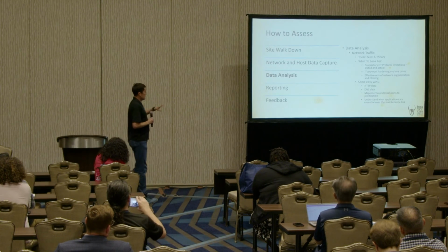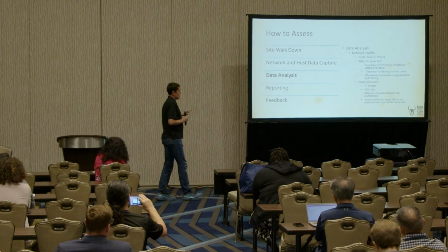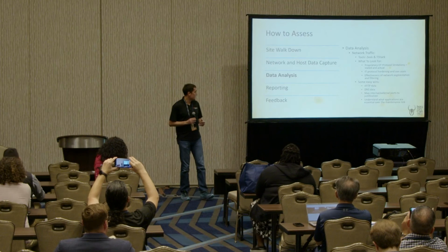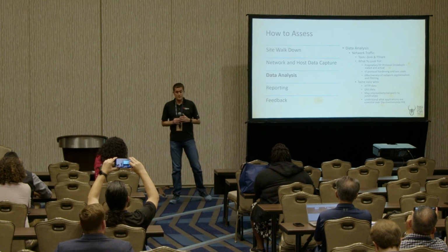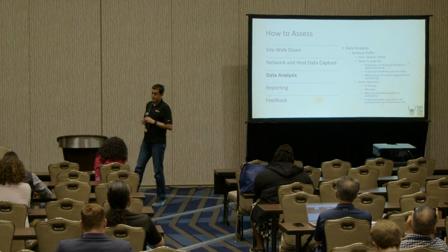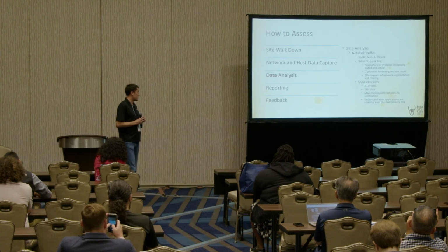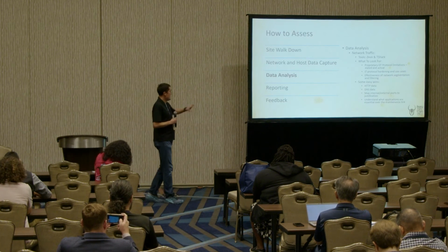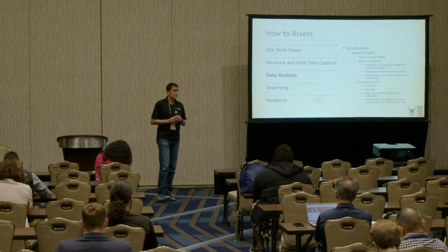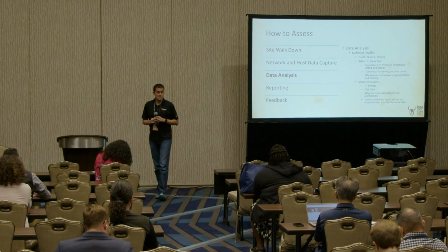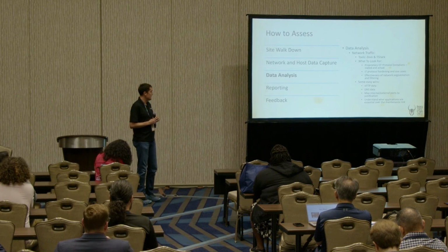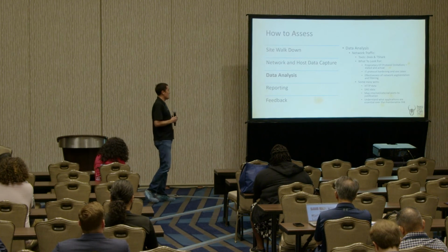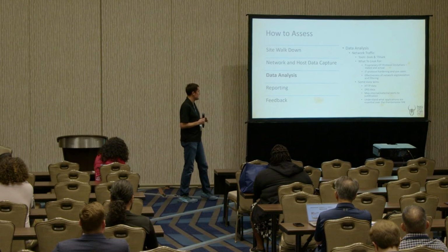Data analysis tools that we like to use are just off-the-shelf Zeek and TShark; there's a lot you can do in there. There are more OT protocol libraries coming out for those, both from DOE and other groups. I know Amazon dropped a lot out. On this maintenance highway, though, they're using a lot of common IT protocols. So if you look at DNS and HTTP, you'll find some really interesting stuff on how a lot of the OEMs are doing business across these.